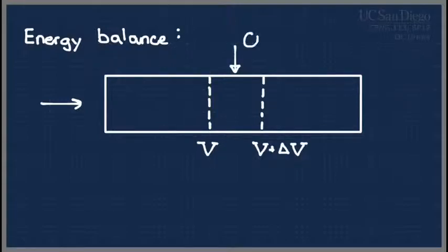So we're going to assume that any amount of energy that goes into the system, we're calling it delta Q because we're dealing with a differential amount. It's typically over the entire volume. But it'll be plus if it's considered added to the system. So if we're, for example, heating it up, it'll be plus because it's coming in. If we've jacketed the reactor and we're trying to cool it down, it would end up being negative because it's going out. So that's all the energy through the walls.